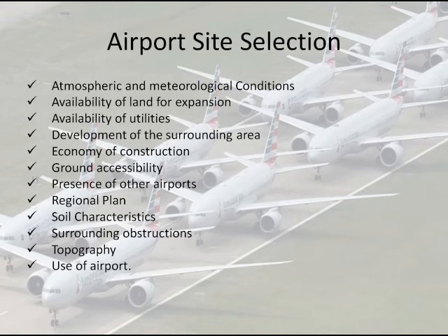The soil containing a reasonable amount of pervious materials like gravels or sand with a suitable natural binder is desirable for the airport site. The most undesirable type of soil is the one having high porosity, or the property of becoming plastic when wet.